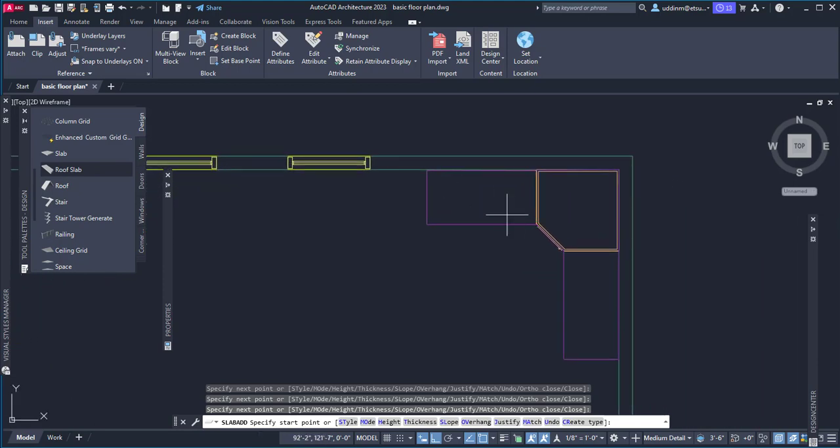Now, the slabs, just like the cabinets, any of the furniture, vases that we've discussed before, any of those kinds of things, when they come in, they're going to come in on the floor level, which means that the elevation is 0, and therefore we need to move it up. So there's a couple ways you can move this up to the top. For this countertop, obviously we want it to sit on top of the cabinets. So you need to know the height of the cabinets, and then you can select the slab and change the elevation to whatever the height of the cabinets are.